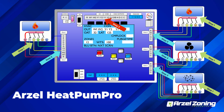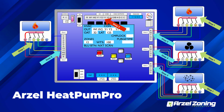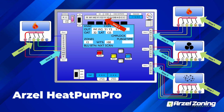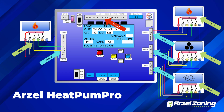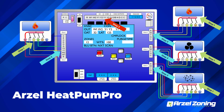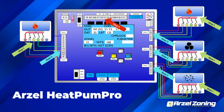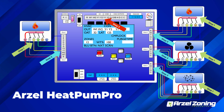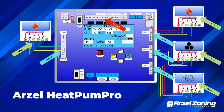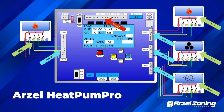Each connection inside the board, zone 1, zone 2, zone 3, zone 4, is our equipment in relationship to that thermostat. And then the zone panel tells us exactly what it's outputting for. And those outputs are a thermostat in relationship to our equipment. So we don't have to try and diagnose all 4 zones in our equipment at the same time. We can break each zone down individually, and then we can break the equipment down away from the zone thermostats themselves.